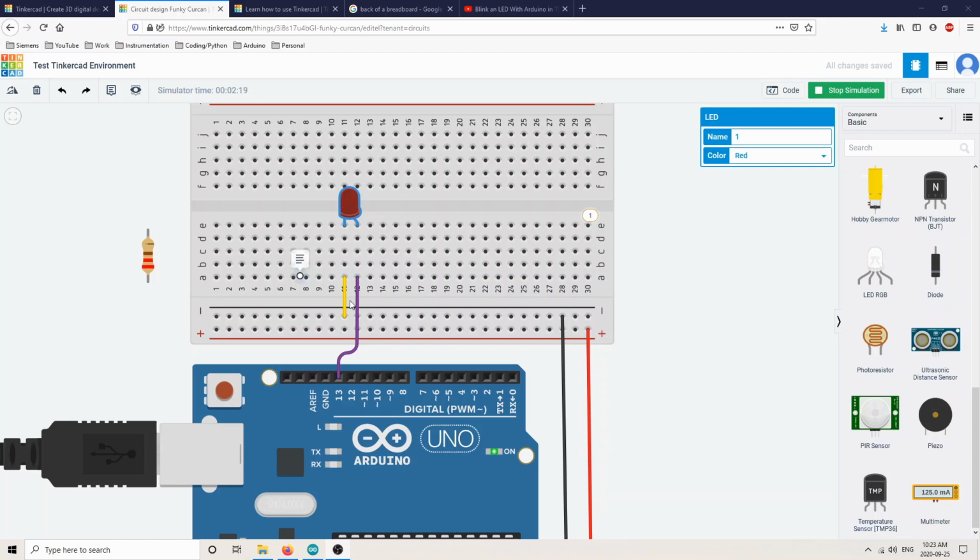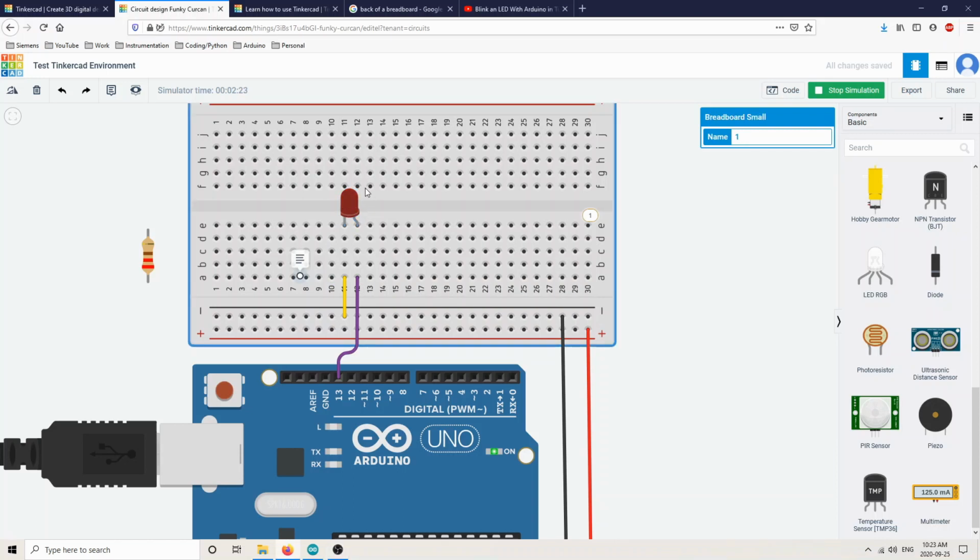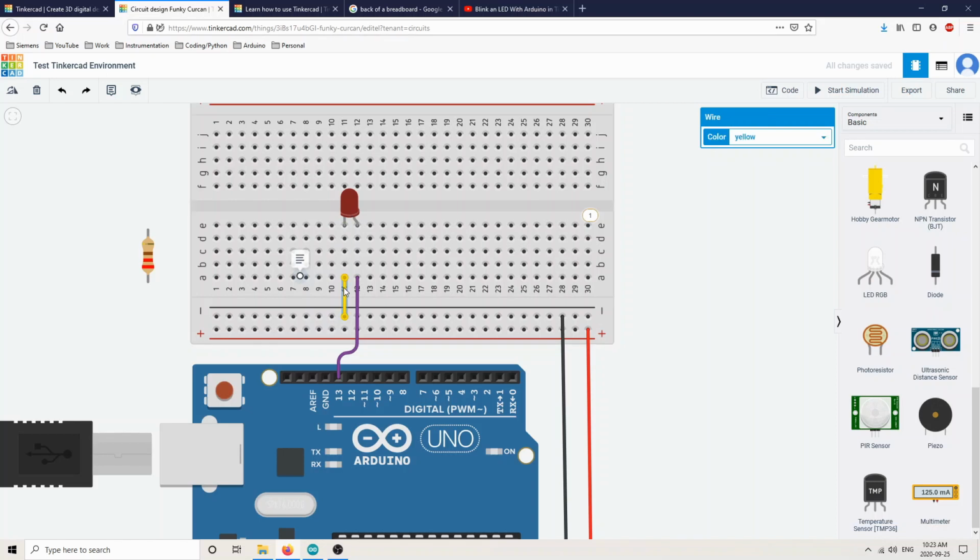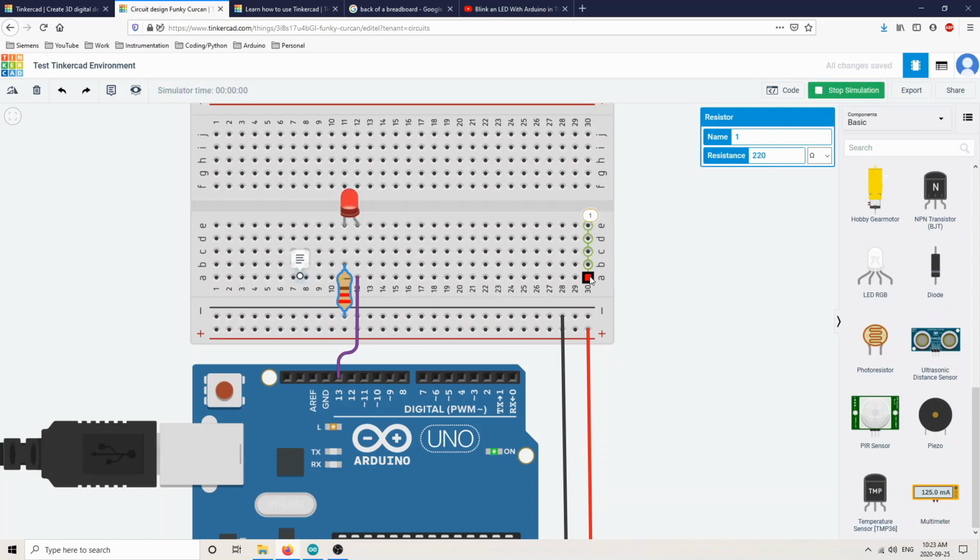Somebody's going to have to help me out because I can't get it to come in. I thought that if you just clicked on that exclamation mark that it'd actually bring it up. And if we hit stop simulation, then the warning disappears there. So if you have an answer for that, you can place it into the comment section as to how to bring up that warning. But it's cool. It gives you warnings that you have forgotten to put in the current limiting resistor. And if I go back to the simulation now everything is cool, and that exclamation mark is now missing on the LED there. Awesome.